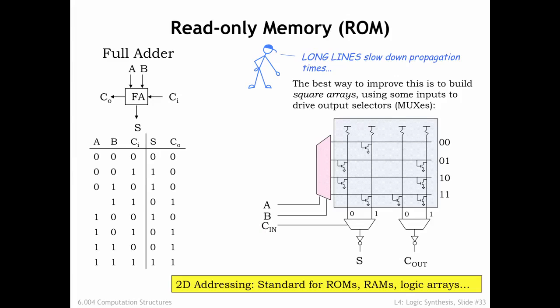For read-only memories with many inputs, the decoders have many outputs, and the vertical columns in the switch matrix can become quite long and slow. We can reconfigure the circuit slightly so that some of the inputs control the decoder, and the other inputs are used to select among multiple shorter and faster vertical columns. This combination of smaller decoders and output muxes is quite common in these sorts of memory circuits.